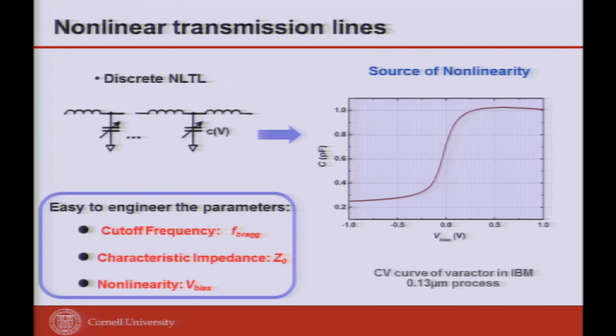But this is rather similar to that L matched into a varactor, but it's in propagation mode. So what my student did wrong is that one implementation is flipped. So it's a varactor, but with alternating CV characteristics. Originally, you propagate a wave on this and a soliton will form, because the higher voltage will propagate slower than the lower voltage. So they form into a soliton.